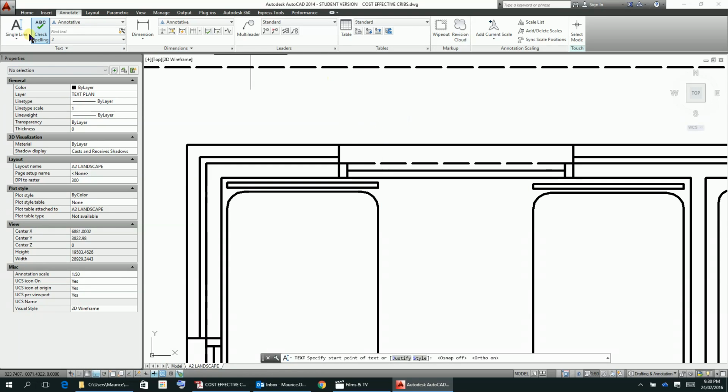Alright, so now I'm just going to go single line, and I'm going to maybe keep it about 1 millimeter above the line, which is probably a good sort of guide for where you want the text. I'll have a little look at that now. 1200 times, oh that's a capital, I'll just go there, times 1400, and that's that done. Now we know that this text is 2 millimeters high, so the gap between the text and the line is around about 0.5 millimeter.